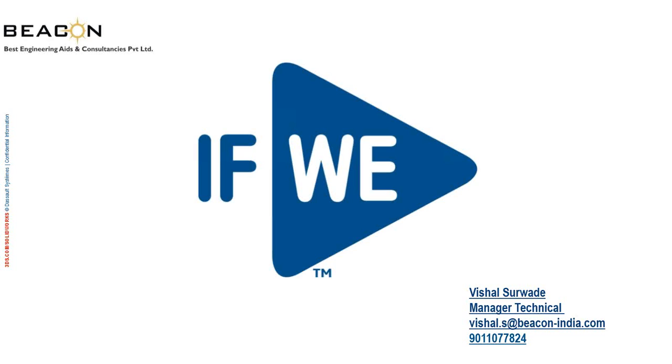I have a query from one of the customers saying, if you don't have a CMM machine and still want to use this tool, what will be the other options available? If you don't have a CMM machine, I've shown that if you have a digital caliper, a USB-based caliper, you can connect it with your computer and measure using that. Or if you know the values, you can manually enter them. So all three options are open. You can enter them manually if you know the values. If you have a USB caliper, you can link it to your computer and those values can be obtained. If you have a CMM, then obviously you can use the CMM machine.